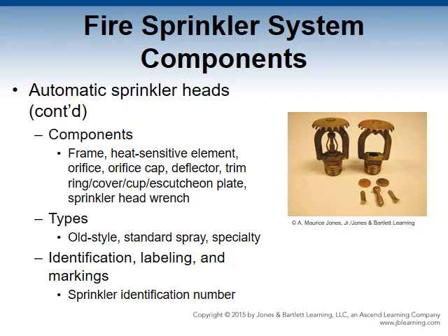Corrosion-resistant heads, which are specified for environments that promote corrosion. Institutional sprinkler heads, commonly found in mental health, correctional, and detention facilities. You have open sprinkler heads, used for deluge sprinkler systems, flowing water from all heads over a large area without waiting for heat to activate them.